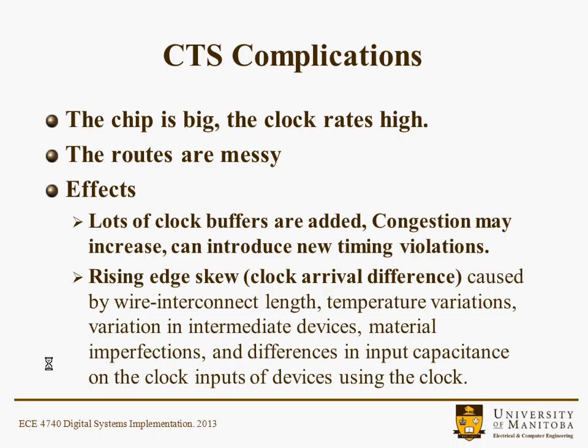What you want to try to do is minimize rising edge clock skew in this particular case, and that's basically a clock arrival difference. And of course, since these are placed all over the chip, the wire lengths are all different. There might be some temperature variations, even locally. And so an awful lot of state-of-the-art engineering goes into building the clock tree.